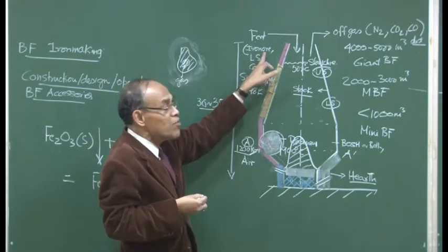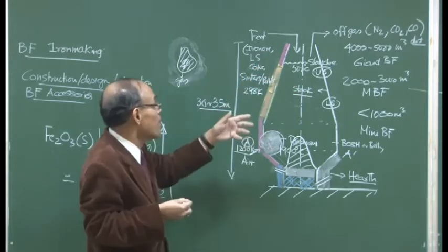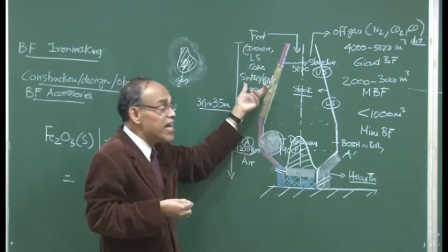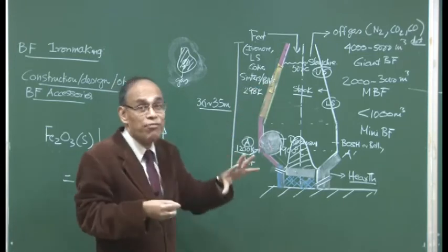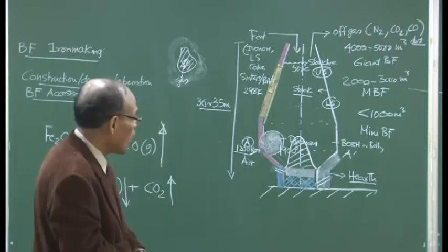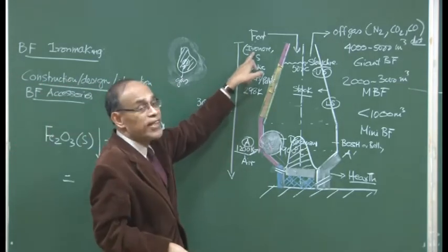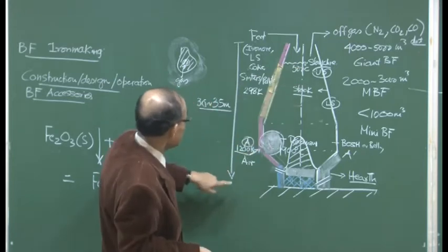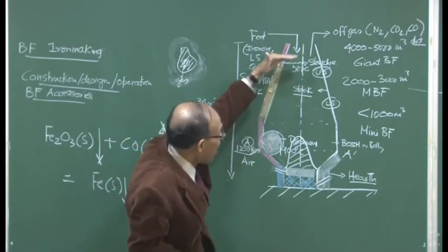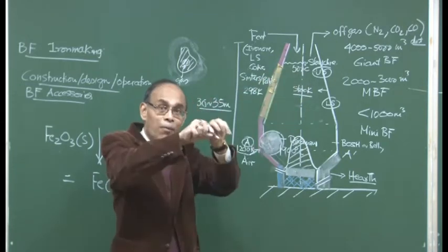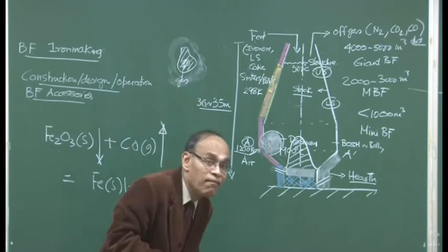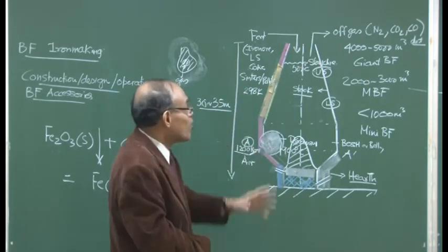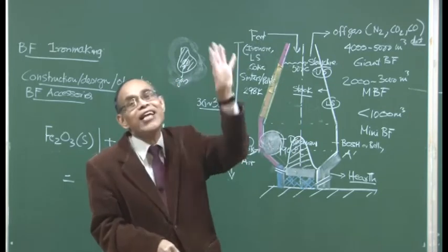Also, you can see that iron ore is what many people charge into the blast furnace, and when we were students, blast furnaces used to be fed predominantly by iron ore, but today mostly blast furnaces are fed by sinters and pellets, because these are engineered materials, and they have tailor-made strength and tailor-made porosities which perform much better than the dense iron ore itself. So, we must also understand, when you prepare these engineered materials, that as the material is 30-35 meters in height, you can imagine how much burden load is acting on a solid particle here. And if the particle crushes, then the gas flowing at a high rate and high pressure will just take all those fines along with the off gas out. So, we cannot charge fine particles inside the blast furnace, they will all be taken away.